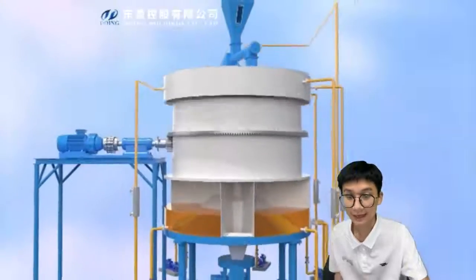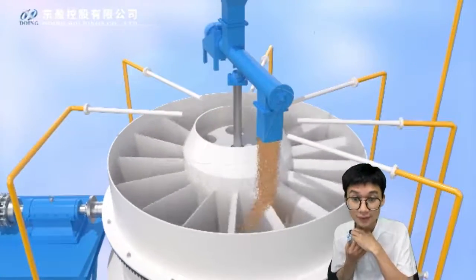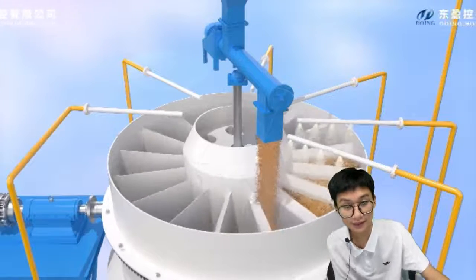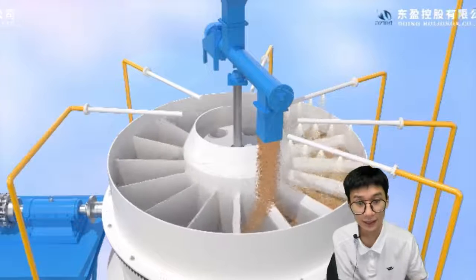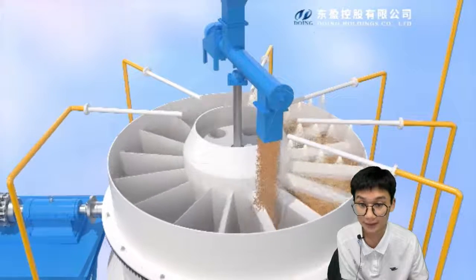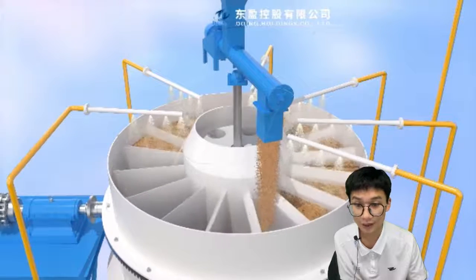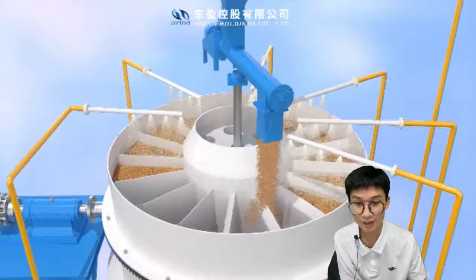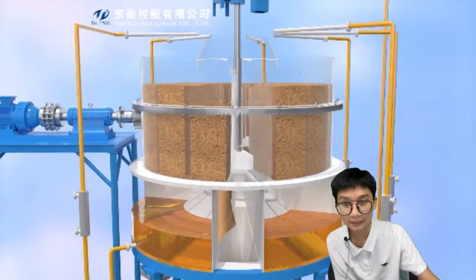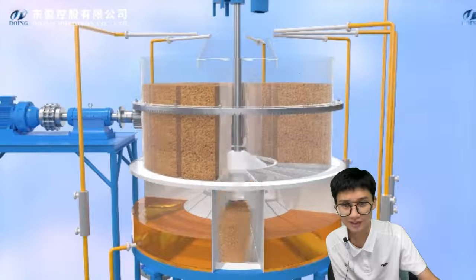And the second difference is about the different oil residue rate. After pressing, usually the oil residue in the cake is around 6% to 7%. By using the solvent extraction method, the oil residue rate can be lower than 1%. The third difference is about the different application range. Both pressing and solvent extraction can be used to process common oilseeds like soybean, peanut, rapeseed, sunflower, sesame, or some oilseeds just like this.